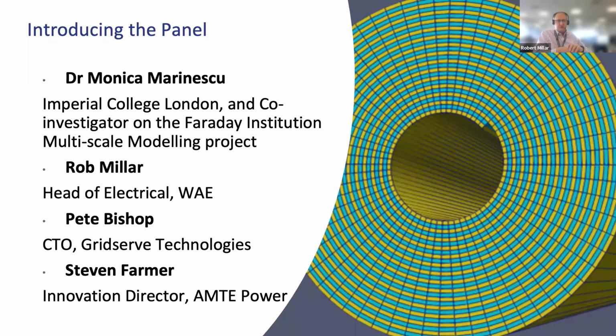So white boxing the model, as we are sort of proposing to do here, gives us much more information. It lets us observe the internal states of every element within the cell, and that gives us much greater possibilities in terms of extracting performance from that cell. One of the other things we get is, if we have a good reduced order physics-based model, then we're able to take that, create a simplified version, and put that into algorithms relatively simply, rather than going through a prolonged process that we have today.